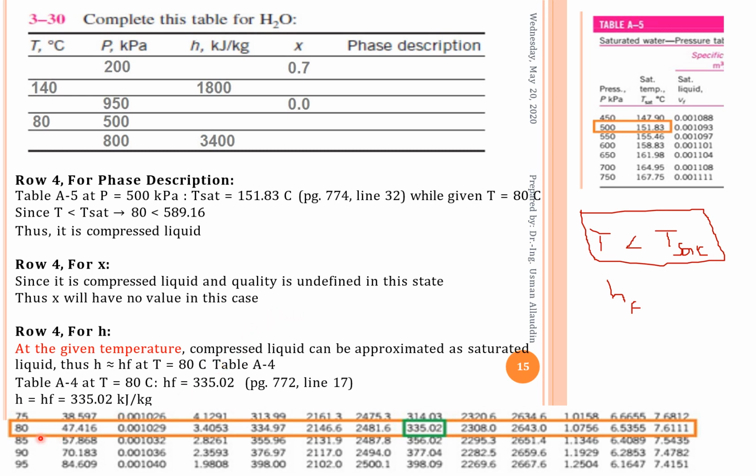And here's one more thing, that after we look into table A5 and want to find our value, we will move back to table A4, and we won't see the pressure there. We will only see the temperature, because our pressure here is less. You can see actually our pressure was 500 kilopascal. There must be 5 degrees Celsius, but that's not the case, because we are in a compressed region. That's how we know that we are actually in compressed region. We will only look into temperature value and whatever we need to find.